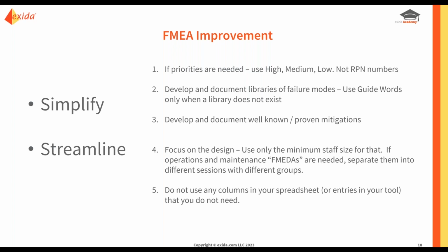Focus on the design, not operations and maintenance. Focus on the design because we're trying to save design man hours, and we're trying to get the design to market in the minimum calendar time. If you need more FMEAs, separate them into different sessions with different groups. And absolutely don't enter anything you don't need. Just because it's in the tool or you have a column for it in your spreadsheet, don't use it if you don't need it. It makes me sad to see some FMEAs where the engineer wasn't actually well trained and ended up using all the extra boxes that are only needed in rare circumstances. Don't use anything you don't need.